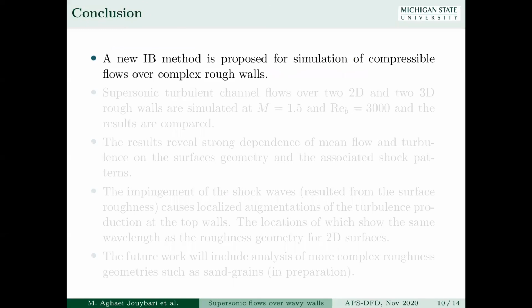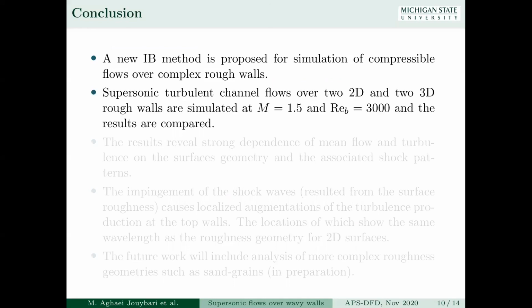In conclusion, a new immersed boundary method is proposed to simulate compressible flows over complex roughness geometries. Supersonic turbulent channel flows over two two-dimensional and two three-dimensional rough walls are simulated at Mach 1.5 and Reynolds bulk of 3000, and the results are compared.